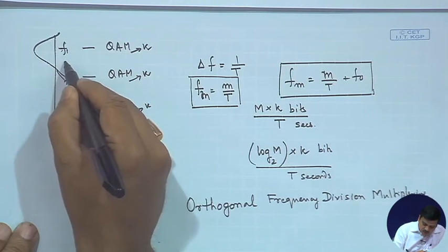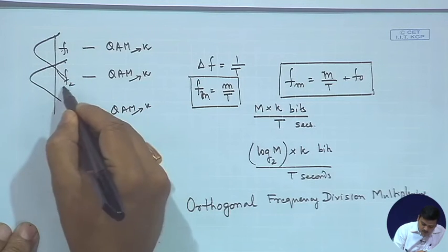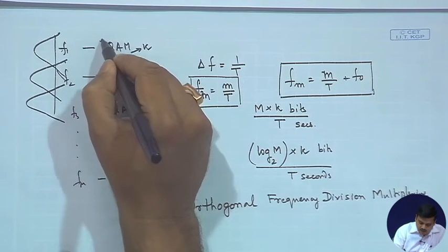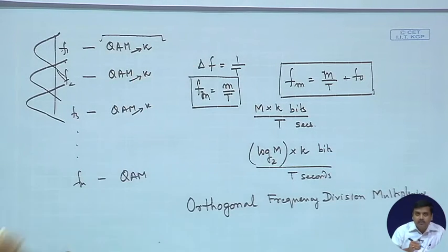So, you have a frequency spectra which looks like this, provided our time domain pulse is a rectangular pulse. So, what we have in this case is the smallest frequency separation while doing frequency division multiplexing. You can't do any better than this, any smaller frequency separation, while maintaining orthogonality amongst the carriers, or sometimes called subcarriers.